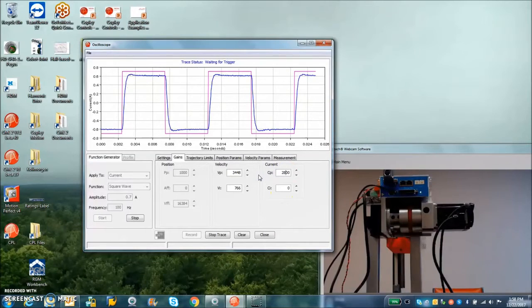I'm looking for the point at which I get an overshoot, and 4,000. So I'm starting to get a little peaking here. So there's a little overshoot. So I'm just going to cut this number in half. Yeah, it's a large inductance. I've got a slew rate limit.